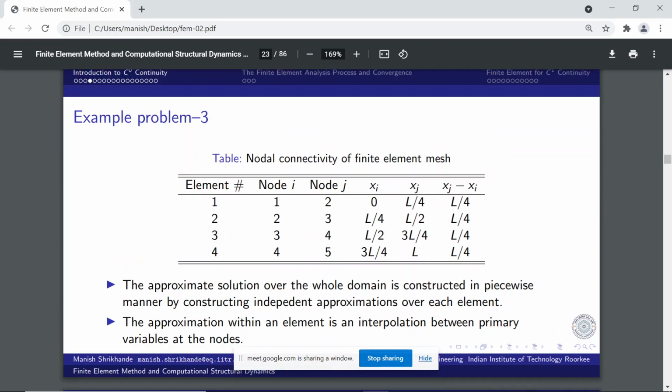So that graphical representation of the mesh is encoded in the form of numerical data. Element 1 is defined by two nodes. Node I, the left side node, is numbered 1 in the global node numbering. The entire domain has nodes distributed over it, and these nodes are numbered sequentially as unique identifiers, and an element is defined by the nodes which comprise it, and the nodes themselves are identified by their coordinates. So five nodes define the four elements, two nodes for each element,